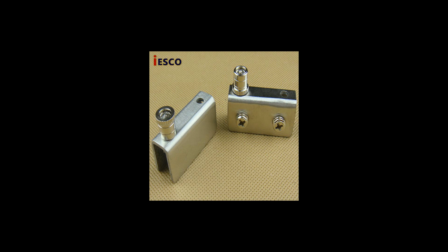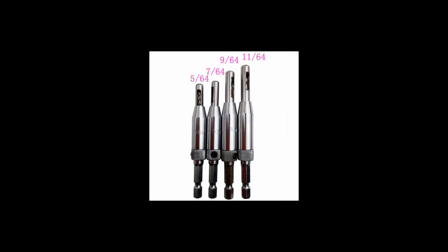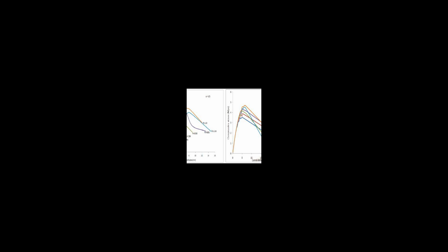H hinges. Shaped like an H and used on flush-mounted doors. Small H hinges, 3 to 4 in (76 to 102 mm), tend to be used for cabinet hinges, while larger hinges, 6 to 7 in (150 to 180 mm), are for passage doors or closet doors.